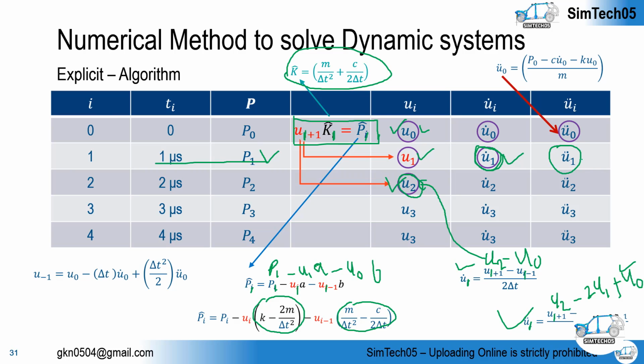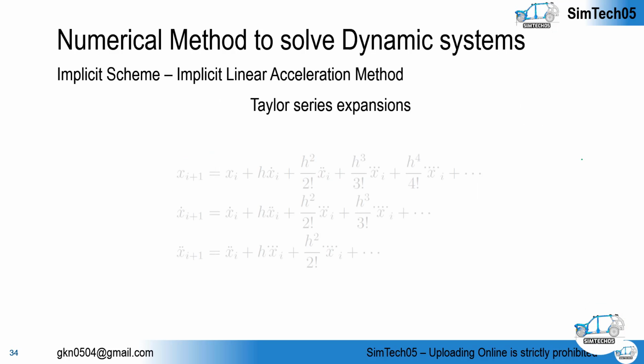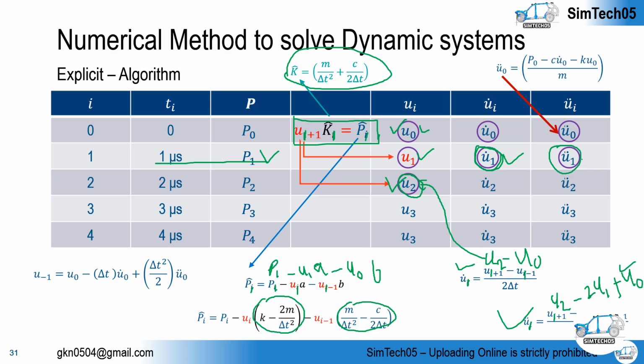So in this way, every unknown parameter in the first increment is known. Now we can again populate the solution for the further increment, and this procedure will continue throughout the analysis. So hope you got the idea how the explicit algorithm basically works and how it finds the unknowns in terms of displacement only. So that's all for this video. Thank you for listening. Of course we also have the beta Newmark method and so on, but we are not going to discuss this in the same video.